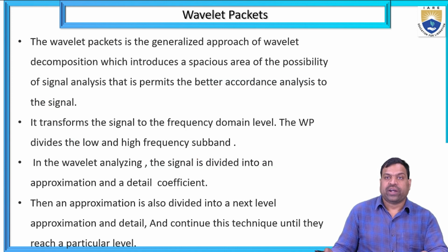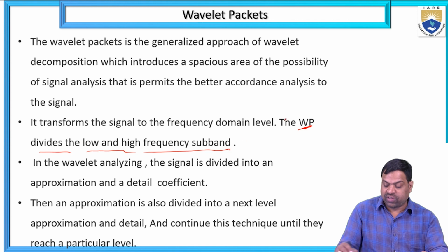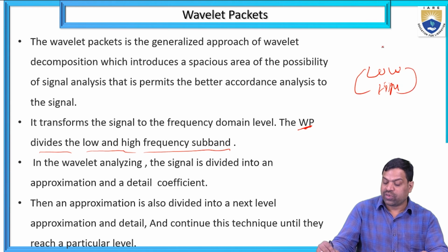The wavelet packet is a generalized approach of wavelet decomposition, which opens up a wider range of possibilities for signal analysis, that is, it permits a better analysis of the signal. In the transformation of the signal to the frequency domain, the wavelet packet divides it into low and high frequency subbands. Only two levels are there, low level and high level. When I'm going for the two levels, low level and high level of the wavelet packet,